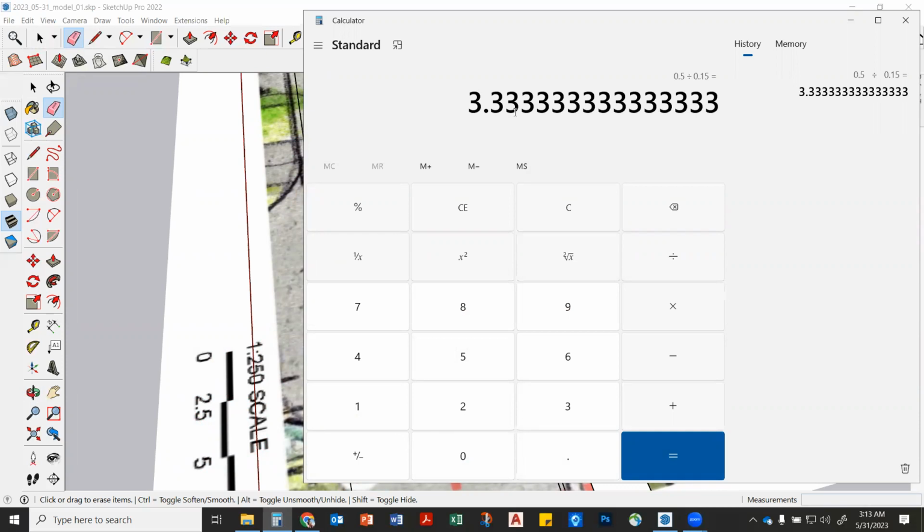How many people have seen third steps? Like steps that are about this big, right? And they're just the right amount to catch your toe and have you fall over, yeah? Depending on the project and the budget, I've seen really bad steps. I'm sure your professors tell you, if you're gonna do risers, make sure they're all the same height. I try to do all the same height across the entire project, because then you're used to that step, that cadence. You don't have these like 80 centimeter ones and then 30 centimeters, so you're just gonna fall over, right?